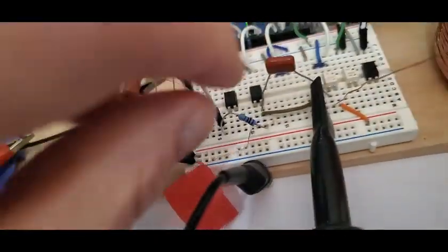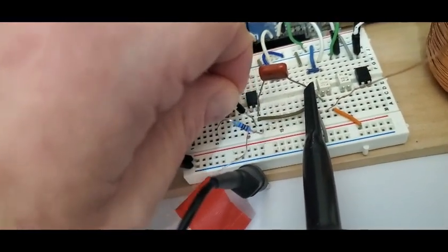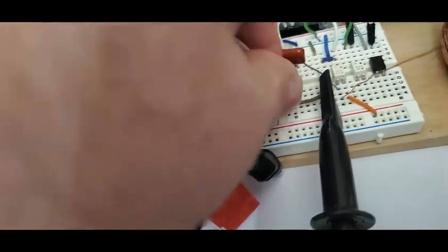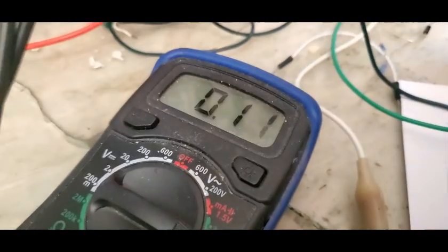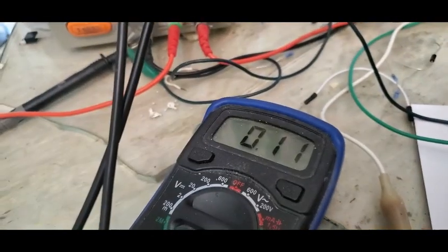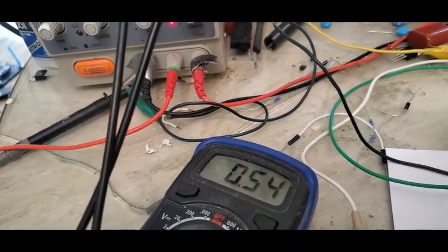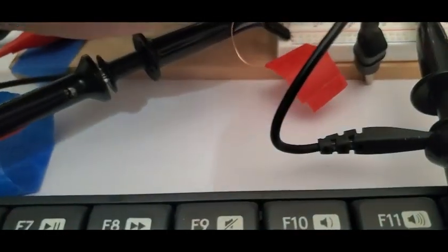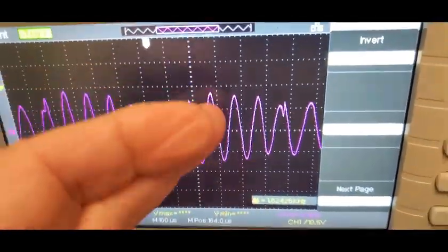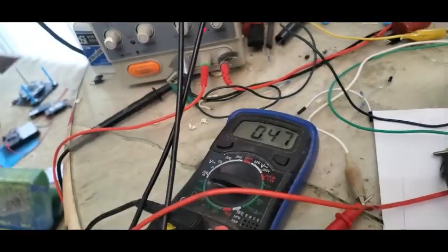So I just put a 470 ohm in there. Well, let me show you the whole thing here. So here's just a direct connection. Looks like that. Here's no connection. Looks like that. And that went from, what did it go from? 0.54 down to 0.12, and then connect it through the resistor. And it's not as good, and this has gone down a little bit, so that's sort of what I expected. I'm going to try an inductor.